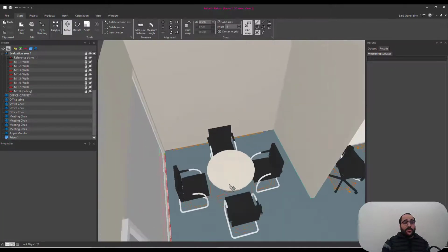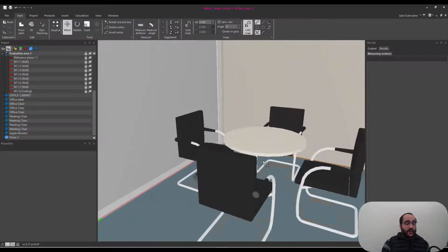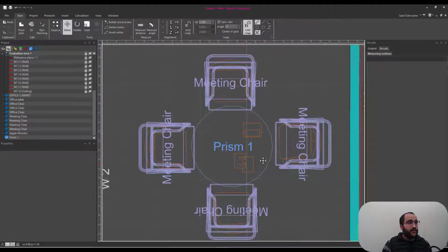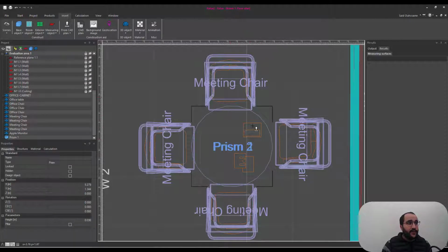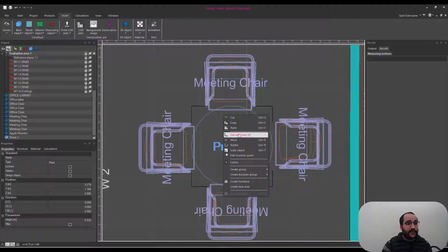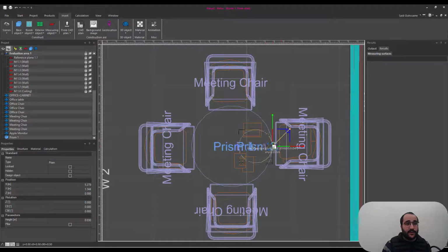This is good. You need to create maybe a leg for that, and for us to create a leg, we can go again to the 2D view, floor plan, and insert from CAD plan, cuboid. You can click on this one again and then Enter, and then we can scale it in this way here.